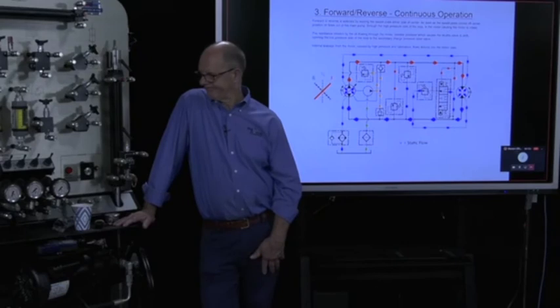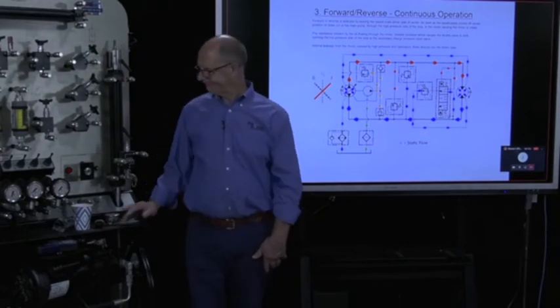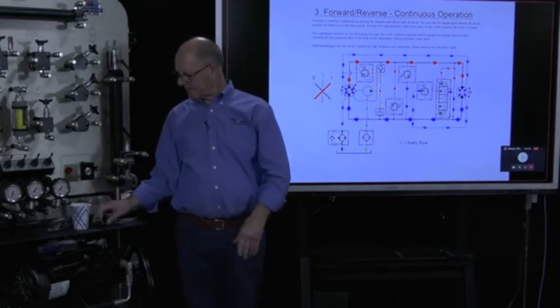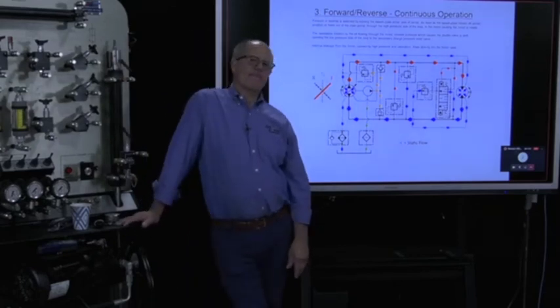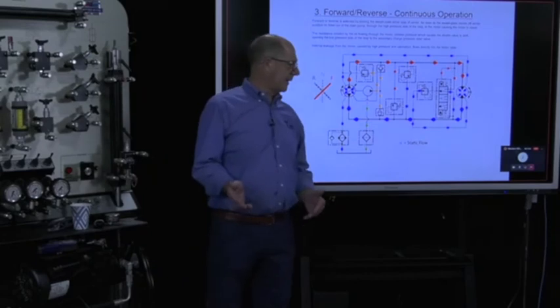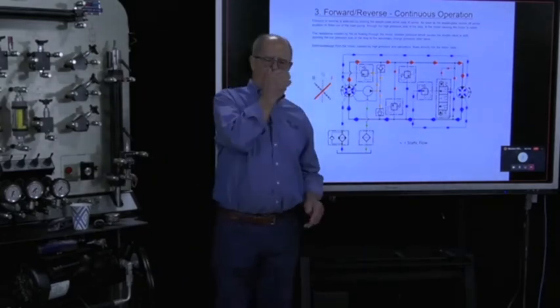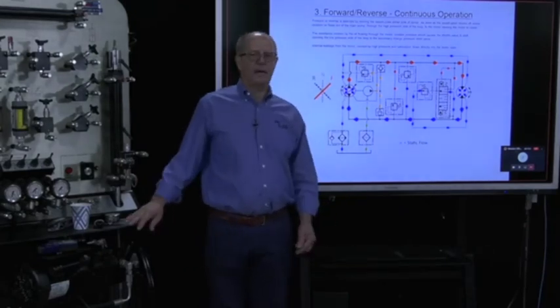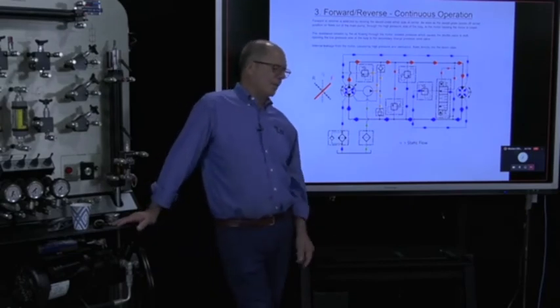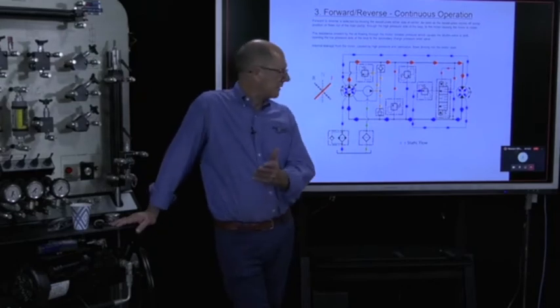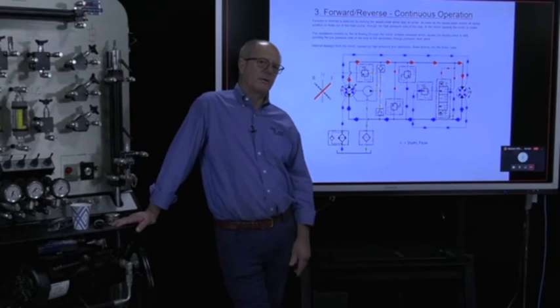Good, thank you, Rory. I do have one bit, I don't know if it's necessary, but the question previously about couldn't debris cut the line, you clarified as you're pushing the projectile. Does that fall in line with what you already answered there? Okay, yeah, I think if you've got debris in the line, and I'm assuming that's exactly what it's all about, and you run a projectile, because the projectiles are really tight, you blow them through with compressed air. I don't see any reason, that's a very good point, why you couldn't go, let's say, across a flat surface that's got a jagged edge on the other side and drive it into the hose and potentially cut it. I think that's a really good point.